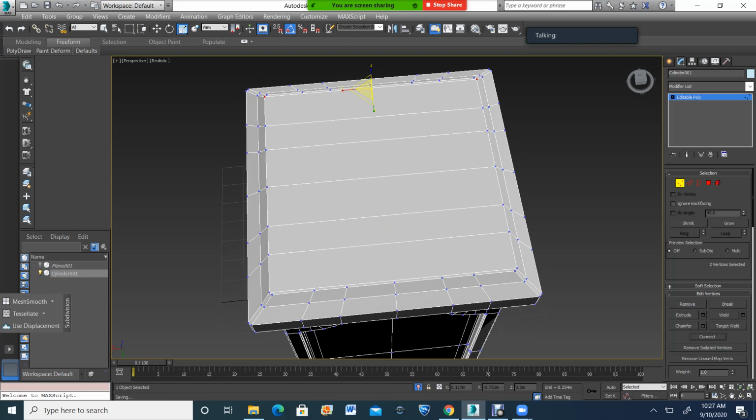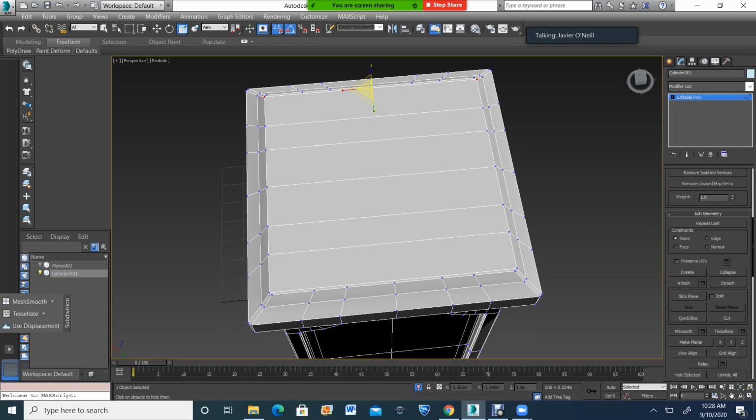And then I hit save. And now I'm going to do a cut on the mesh so I can do the ones that go in this direction. So instead of connect, the first thing I'm going to do is turn on snapping, because you need to snap the cut. And then if you scroll down, you can see cut right here. If I start with this top one right here, and then go all the way down here,